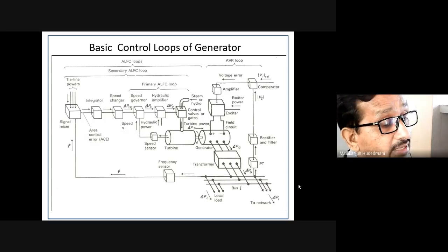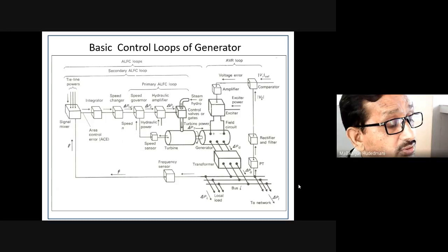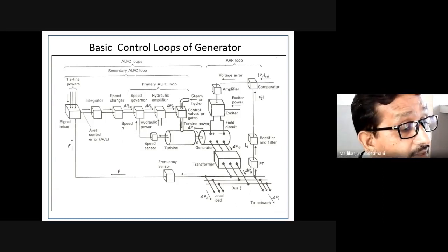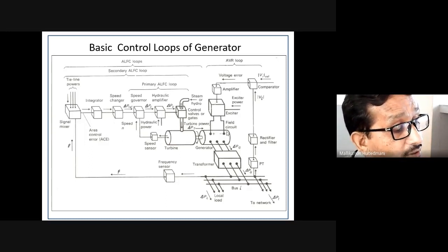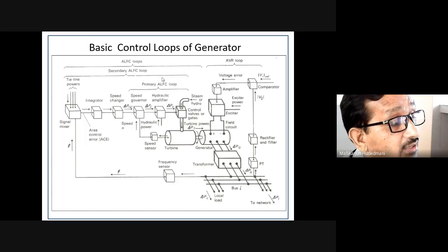The automatic generation controller, concerned with the generation aspect, has to look after managing the terminal voltage, look after AVR, and manage the actual megawatt delivery, balancing it for contingent changes in the load from the variation you notice from the frequency perspective. Actual megawatt is managed, and terminal voltage is maintained. So this has to be in sync.